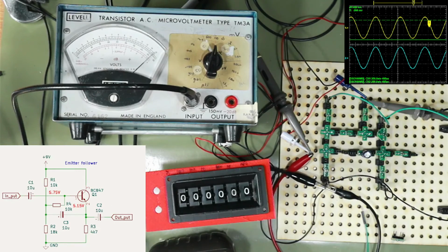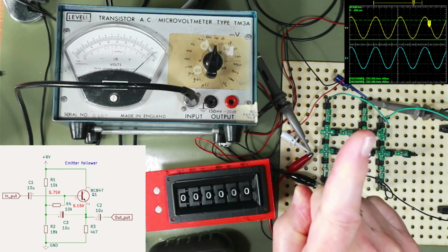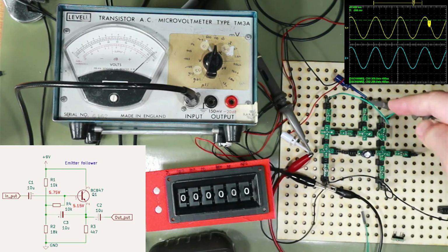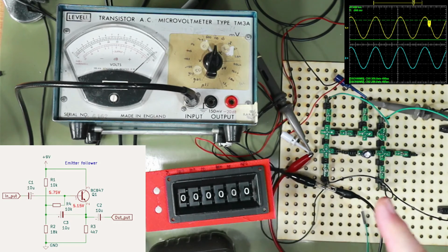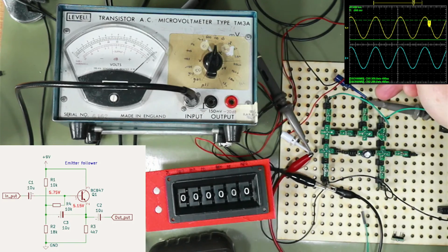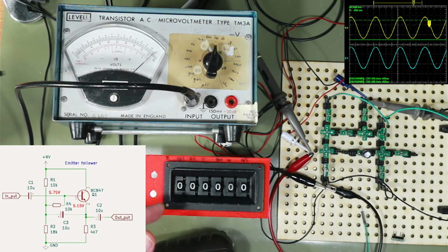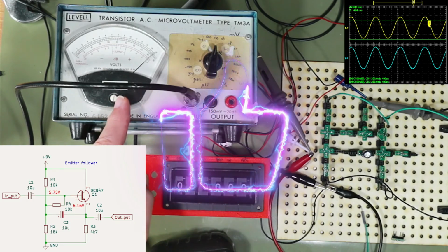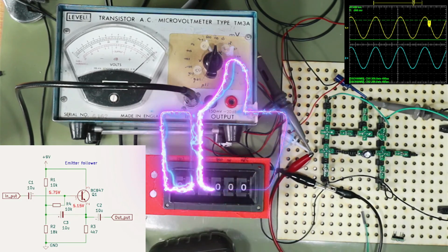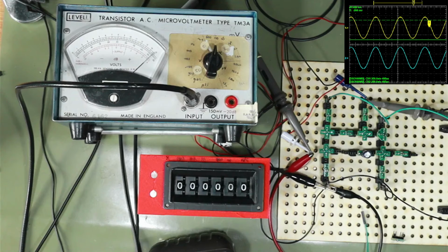Right, here's a bit of a cluttered up screen. We have the scope up there showing you the signal generator output on yellow and the input here on blue. We have the microvoltmeter, and that's going to be measuring the voltage at this point as well. This is my series resistance on the input, so when that has dropped by half or 6 dBs, the value on here will be the value of the input impedance. And there is the circuit, just to remind you, because I'm now going to take that away as I want to bring another meter in for a few seconds to look at the voltages. So we'll just pop that out the way.